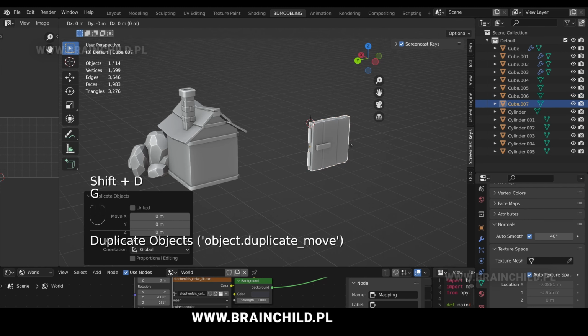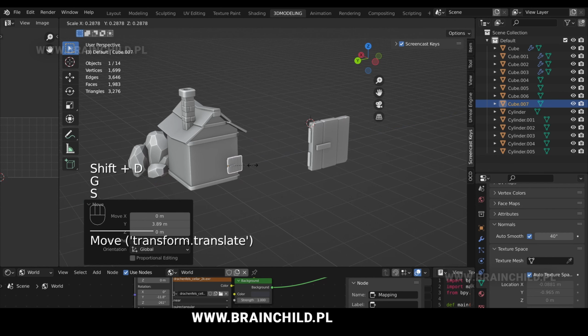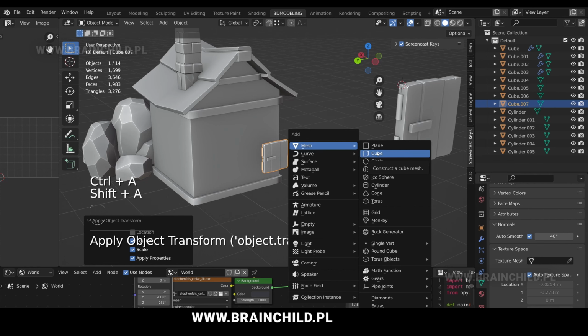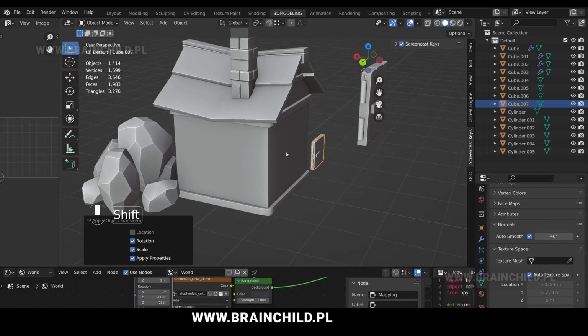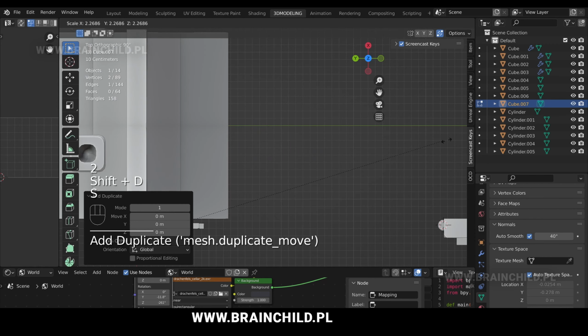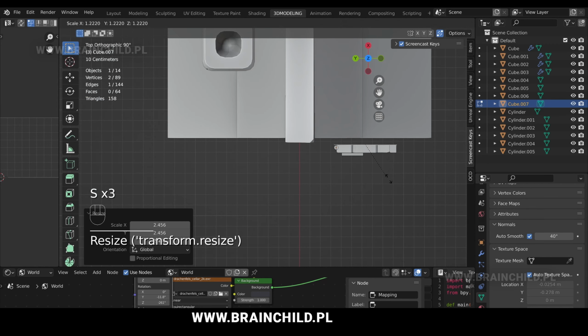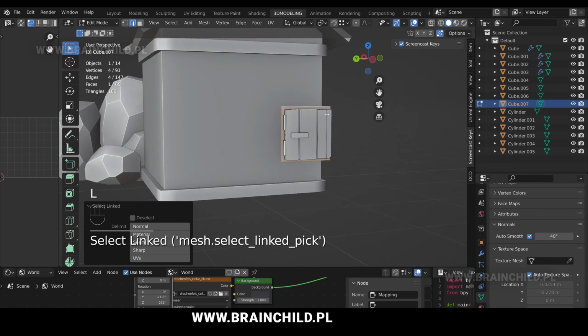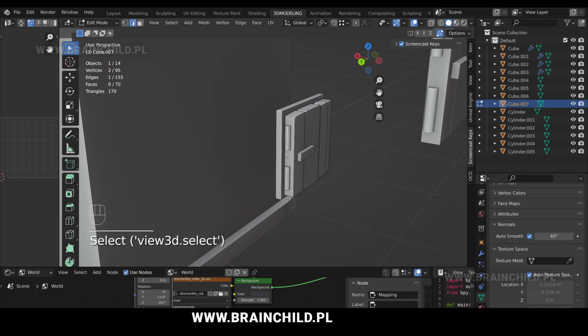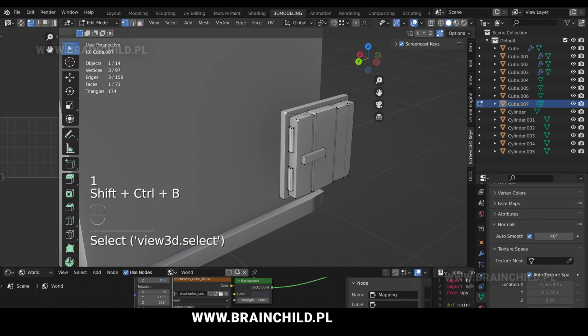The origin point should be on the left, because we're gonna use it to rotate the window so it opens up like a regular window. Select the edge in the edit mode, scale it up by pressing S. We're gonna create a frame for the window by extruding the edge and extruding the face with E button. We can also bevel some of the edges if you want.